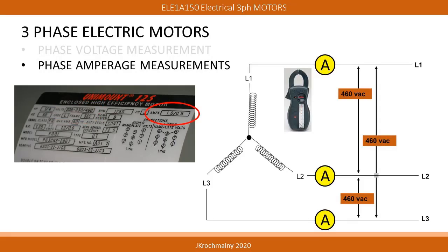In this graphic, we see an amperage rating of a properly loaded motor. When under a load, this motor's amperage cannot exceed this value. Powering the motor under a load, we measure amperage by using a clamp-on ammeter to record the value. Once recorded, we can compare the actual condition to what it's supposed to be.